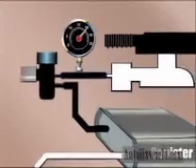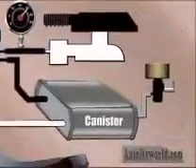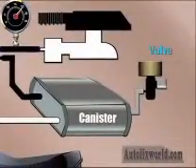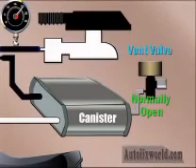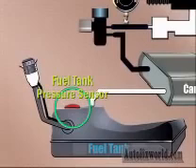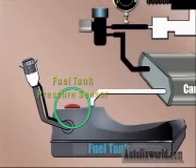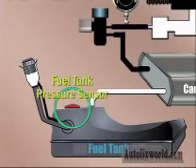A solenoid-operated vent valve is located in the canister vent line to the atmosphere. Unlike the purge valve, this solenoid-operated valve is normally open. The addition of the vent valve is unique to OBD2 vehicles with enhanced EVAP systems. This valve allows the system to be sealed for leak detection purposes. Finally, a fuel tank pressure sensor measures vapor pressure inside the fuel containment system. Also referred to as the fuel tank pressure transducer, this sensor's measurements can be viewed in DataStream if the serial data interface supports the PID.